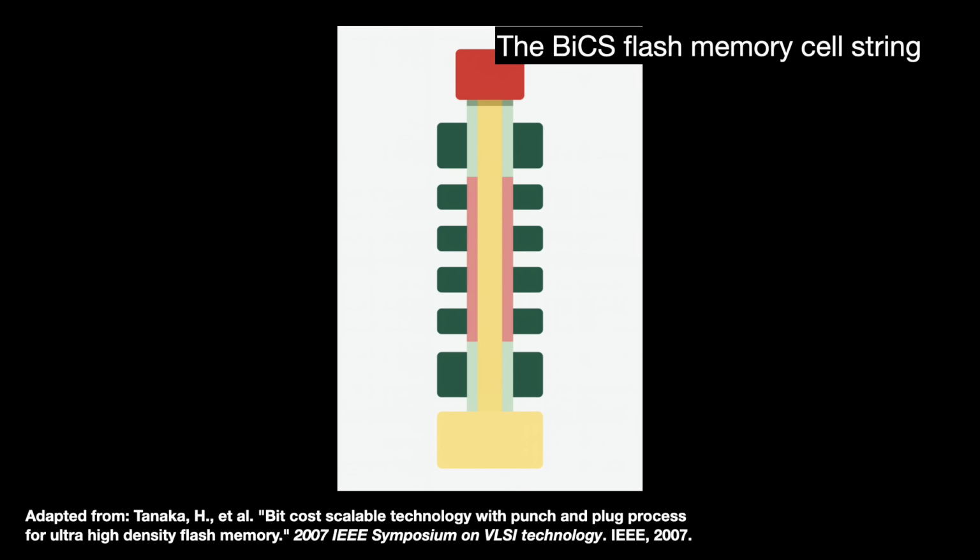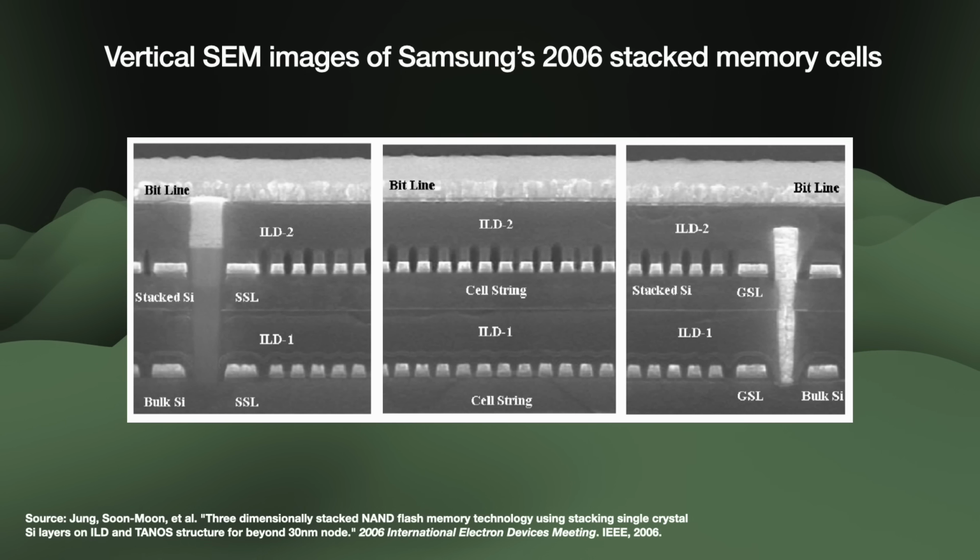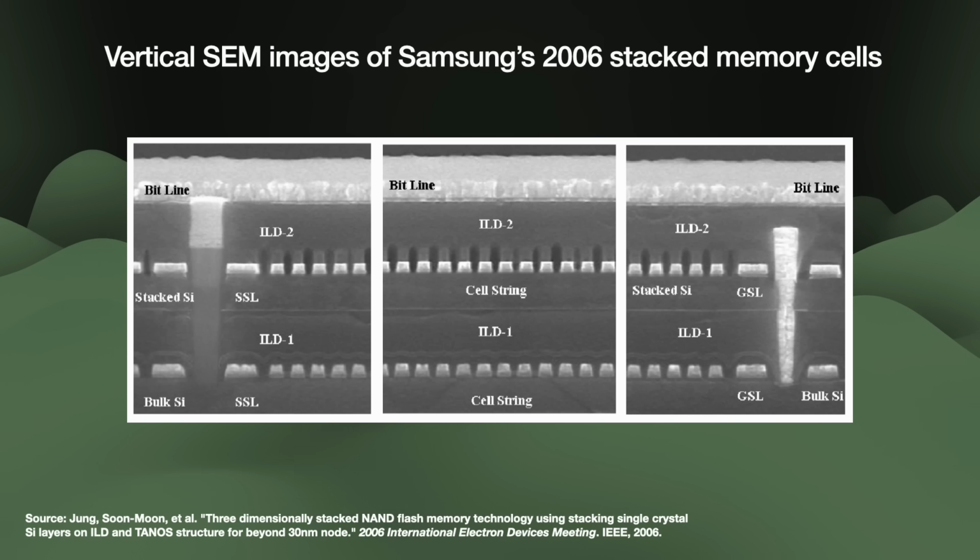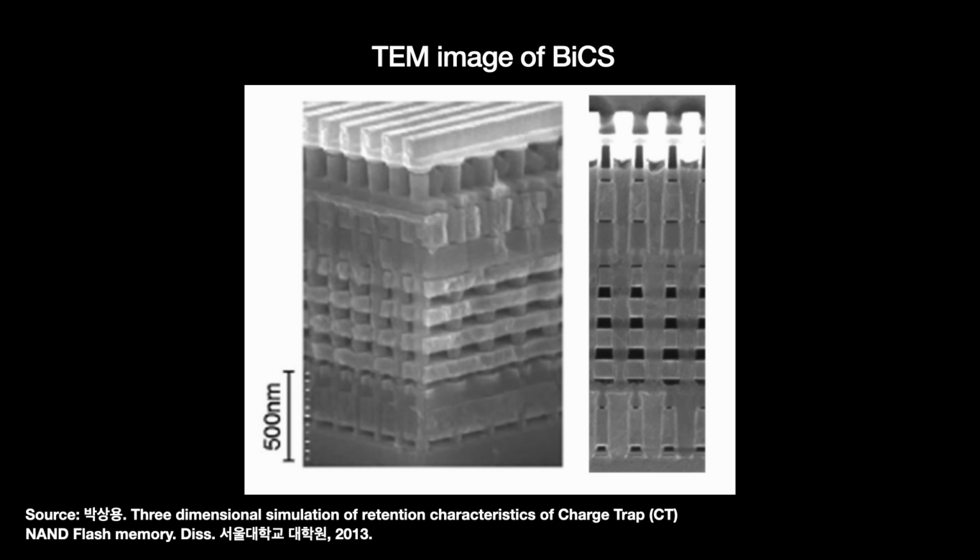The hard, expensive stuff, lithography, etch, channel filling, etc., is done as single steps. So whether the NAND has 1, 3, 5, or even 50 layers, we only need to do that hard lithography and etching stuff only once. There are caveats to that, of course, but that's the gist of the issue. This is how we can so suddenly get 3D NAND stacks 100, 200, even 300 layers high.